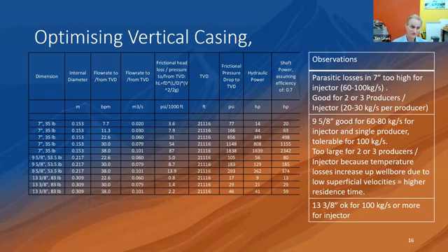I commend you to do this because it rapidly tells you, for our case, we're flowing at between 60 and 100 kilograms a second, or that's the fourth column in, that's the meter cube, so kilograms is 1,000th of that. And as you can see, you need a 9 5/8 on bottom to get a tolerable pressure drop across the well. And I've translated that into shaft horsepower, because ultimately, if you're generating power, then you need to look at the parasitic loads on that power before you export.